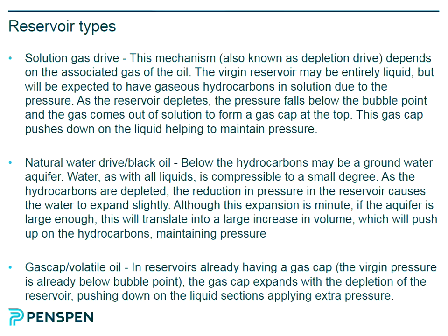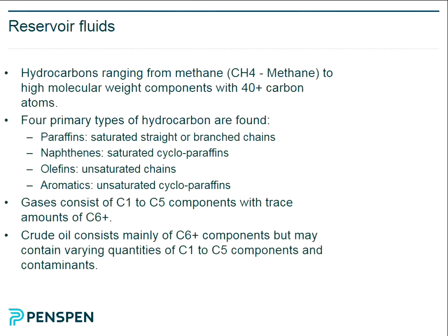Also, you get things you don't want as well. Certainly, water is very, very common, whether it's gas or oil. Water is typically there. Often, that water is completely saturated with salts, and those salts can give you corrosion problems and also scaling problems. When you reduce the pressure and the temperature, they come out of solution. And when they come out of solution, they can actually form solids.